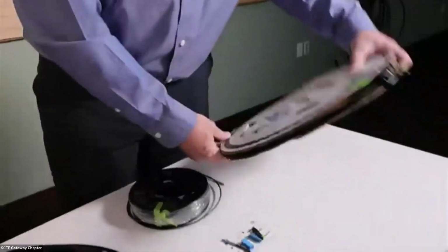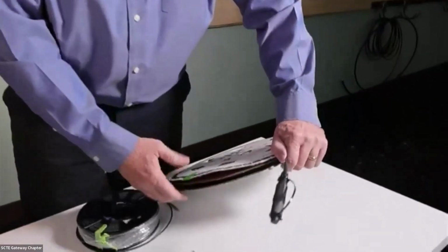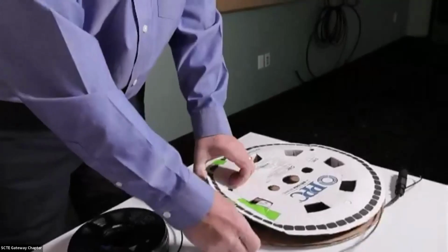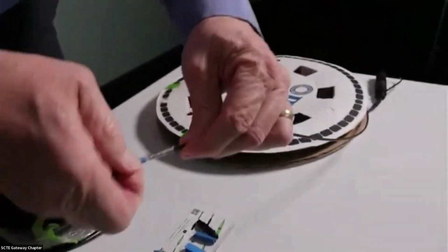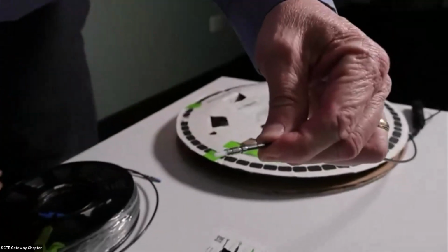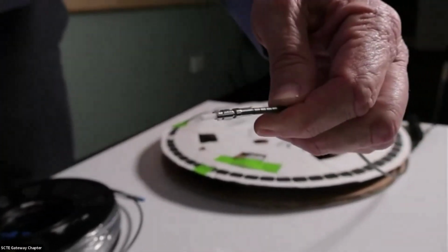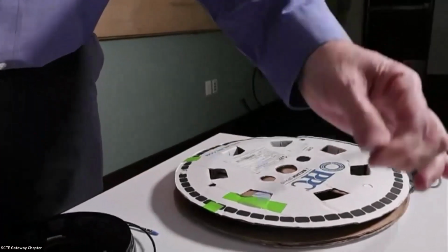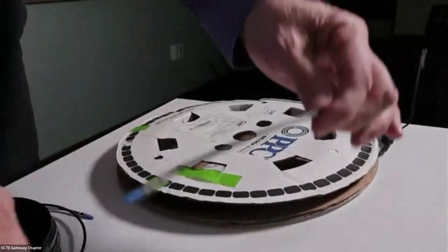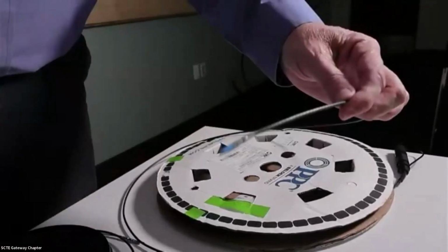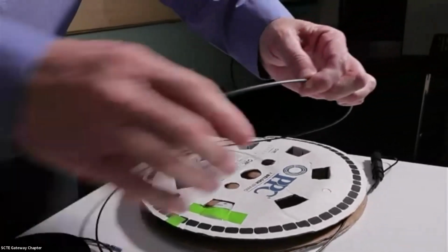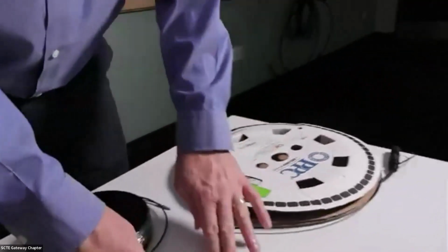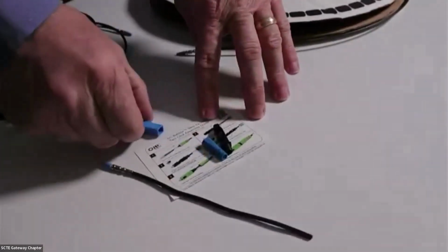So this is an underground drop. There's no messenger on it. It still has an HFOC connector on it. But the house box side is semi pre-connected. It's pre-terminated. It has the porcelain, the ceramic ferrule already on the end of it. Right? So this fiber is designed to be brought into the location where you want, and then a connector is attached. These parts here are used to put the connectorization on it to be attached to the bulkheads inside the house boxes. So we brought some of these as an example, if you haven't seen these before, of how this works.